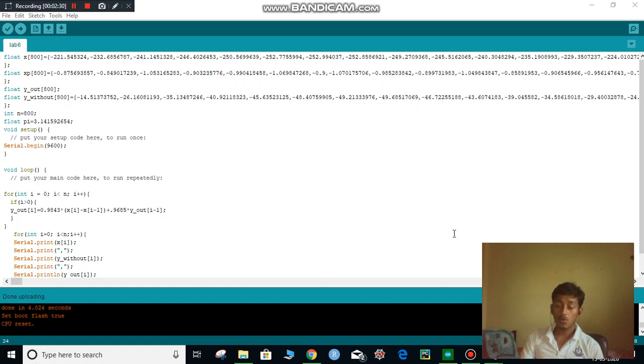0.9843. So our complete H(z) is 0.9843 into (z minus 1) divided by (z minus 0.9685). By rearranging the terms, we get y(n) = 0.9685 y(n minus 1) plus 0.9843 times (x(n) minus x(n minus 1)).